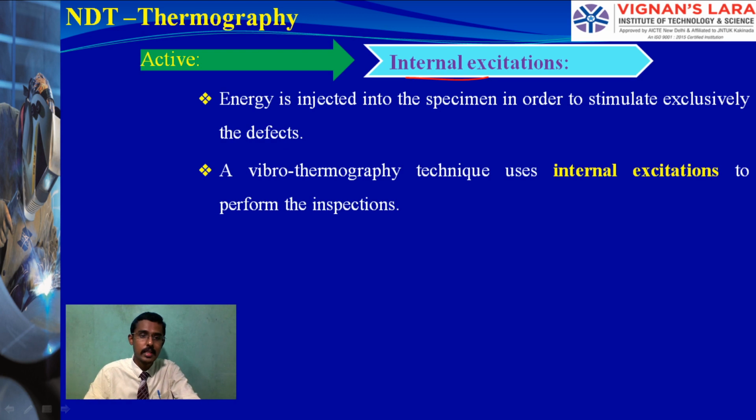But heat has to be generated first. For that, we use vibrations over the specimen. These vibrations make the molecules vibrate and move here and there, which generates heat energy over the specimen. If there is a crack, the heat will be distributed and it will initiate a high point, so that we can capture it through the camera.